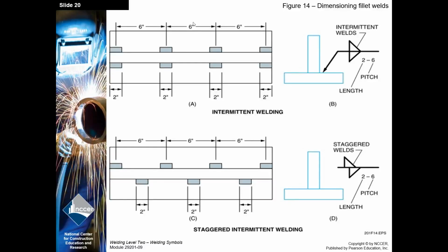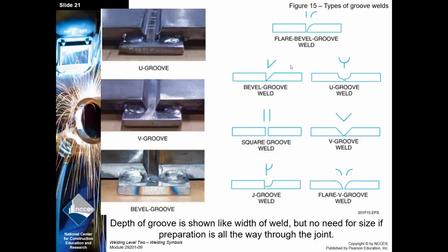So I'm coming to the 10 here, and I'm going to drop 3 and gain 3 and put my center mark. And because they're 2-inch long welds, once I find that center mark, I'm going to add 1, subtract 1. And then I'm going to go 6 inches from the center, add 1, subtract 1. And I'm going to soap the start and stop of my MIG welds here, to make that nice and clean, a pretty fabricated project there.